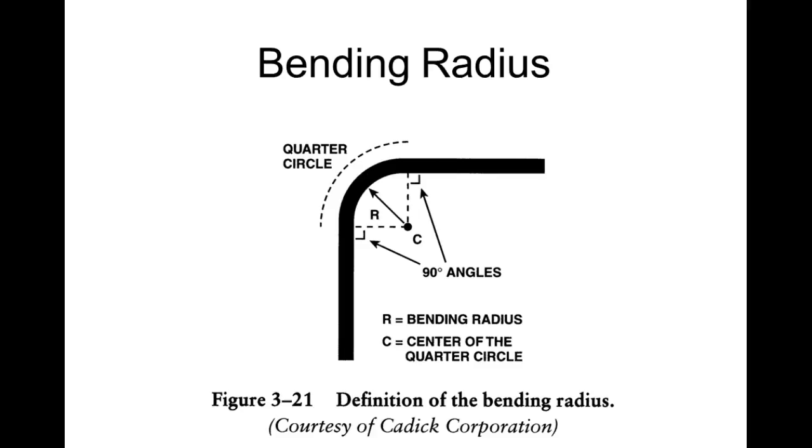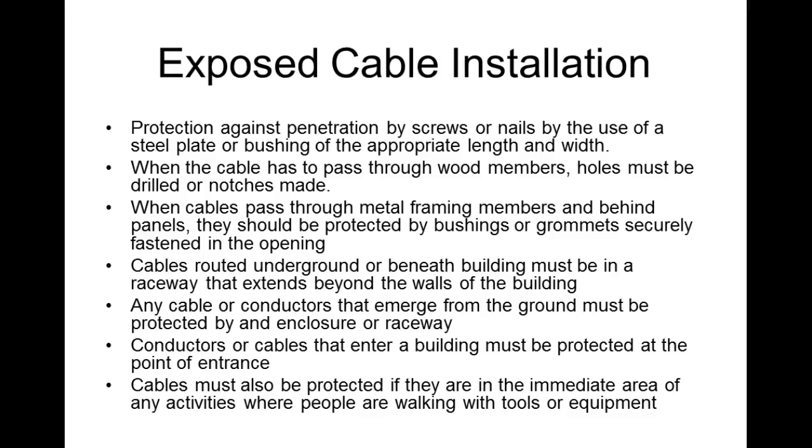And guys, I think we're going to look at protecting cable insulation against penetration of screws and nails. We run into this a lot, especially in house wiring, where we use all these cable nails, these U-shaped nails. People will drive those things in and get them in there too tight. People don't protect the cable.